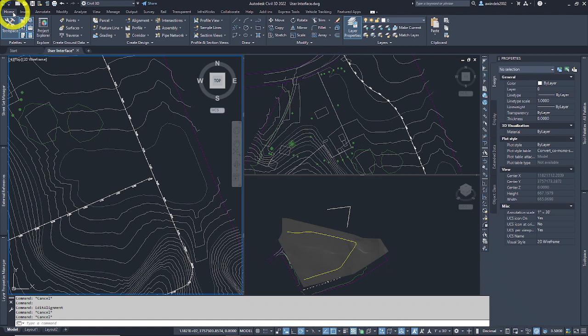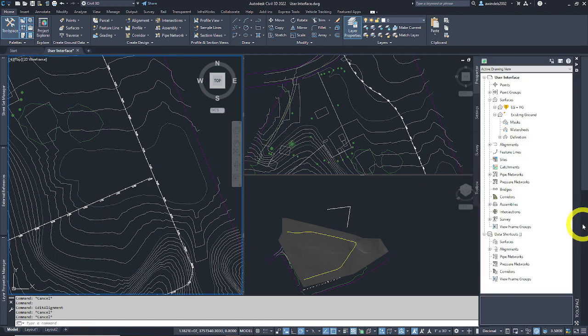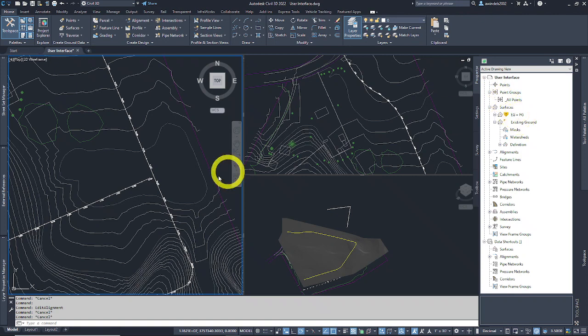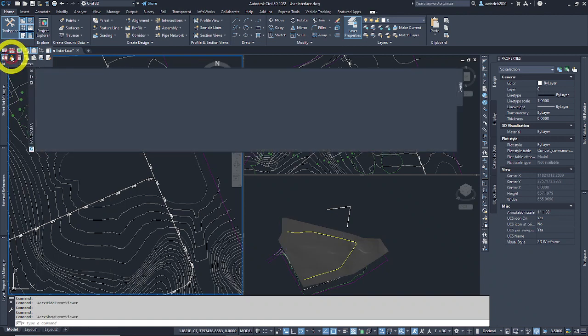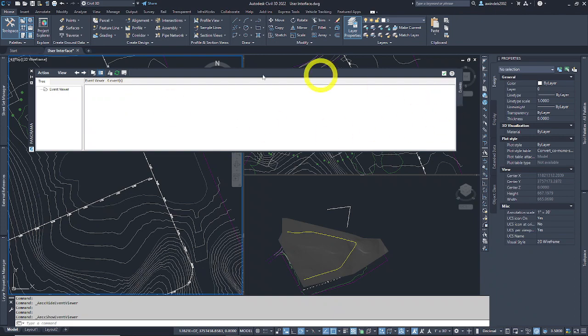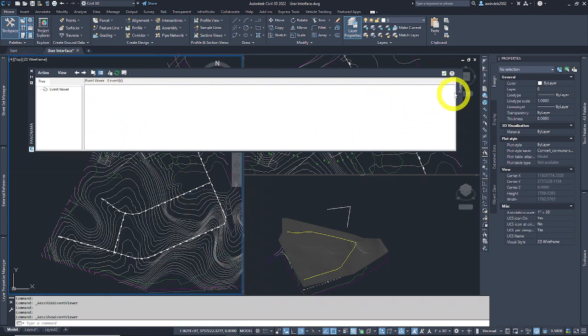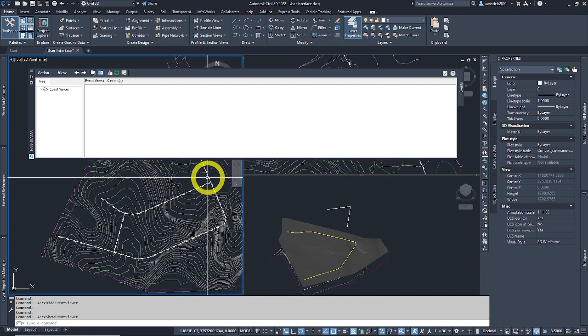It's an extended area to see more design information in Civil 3D, from anything from COGO points to alignments to about anything you could think of. But it's only certain things that engage it. So let me turn it on. It's also called the event viewer. So I have it on and off here. Certain things will prompt it and make it turn on. Not everything will. It has different tabs though, sometimes come errors, geometry editing, various things like that.